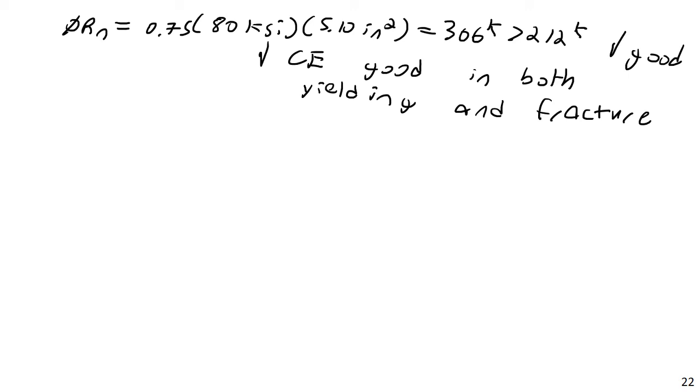I said previously there are sometimes dimensionality requirements, like you have to have bolts a certain distance away from each other, etc. But bolt stagger does tend to give you a slightly higher length of failure plane in certain cases. So that might be a case where it would actually control. There might be times where you deliberately induce a bolt stagger for the purposes of having a longer failure plane and thus a slightly higher failure capacity.